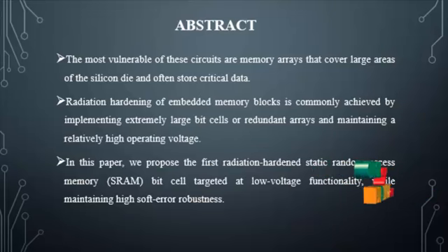The proposed 13T employs a novel dual driven separate feedback mechanism to tolerate upsets with charge deposits as high as 500 fC at a scaled 500 mV supply voltage. This is achieved with a cell layout that is only 2 times larger than the reference 6T cell drawn with the standard design rules.